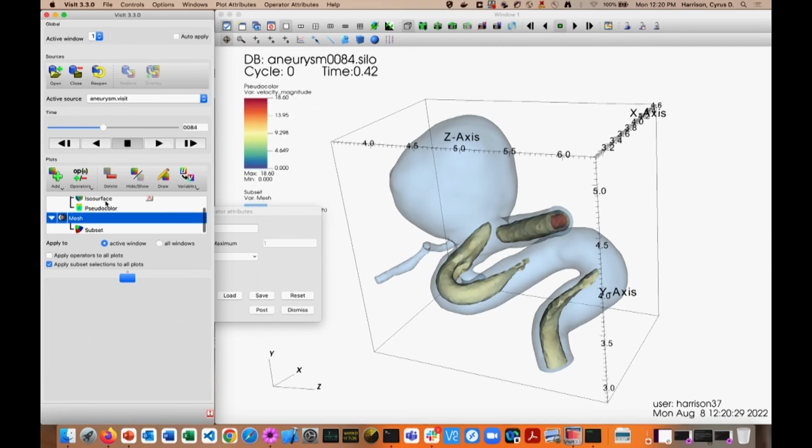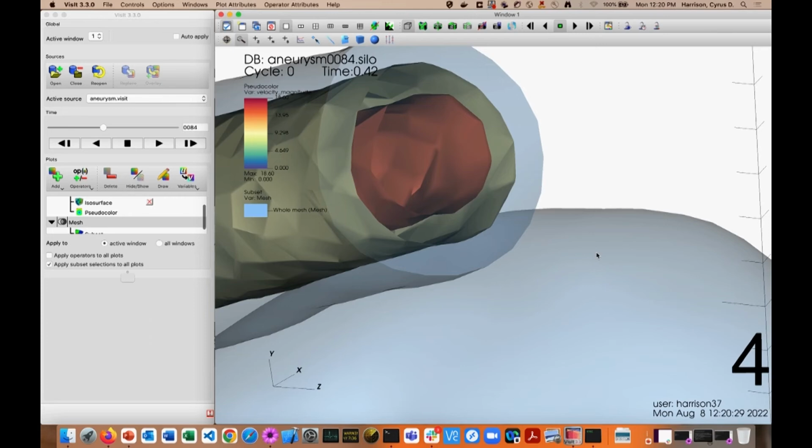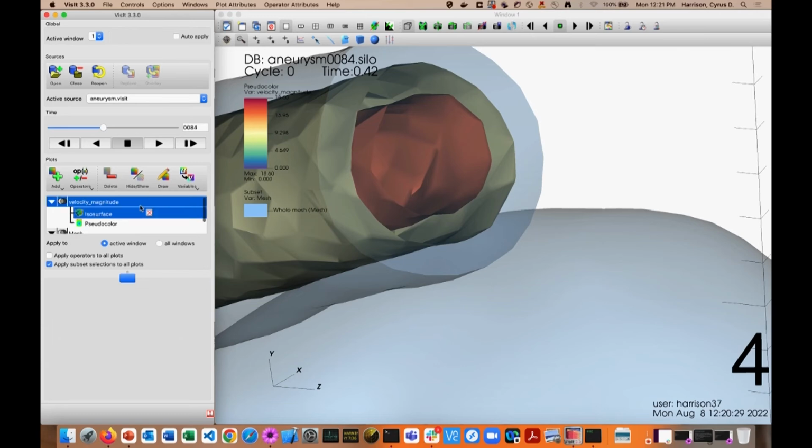Another thing I want to point out is isosurface is a nice way, but you might not always know. Isosurface is a level set at a precise place, a surface in this value. You might want to sweep a volume instead. So if you look in here, you can see we got a lot of stuff going on here, but ultimately it's really a couple different surfaces, right? We know those surfaces are at 10, 15, and 20. But what if we cared about the structure where everything is moving fast? We can do that with an isovolume operator.